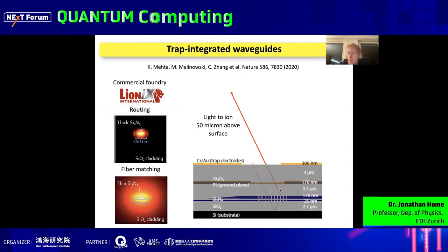The gratings, how do they look? They're written by E-beam lithography. So you'll see one of these silicon nitride wires, or waveguides, coming in here, delivering light. There's a taper here, which adiabatically expands the optical mode. And then a 300 nanometer period E-beam grating, which is curved here to allow the light to focus out of the chip and focus at the position of the ion. And it's carefully designed to do that.